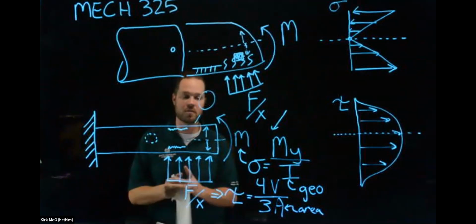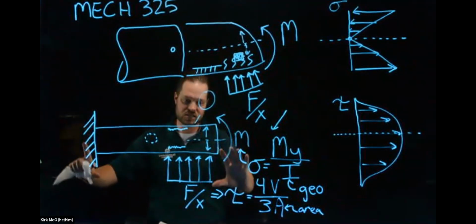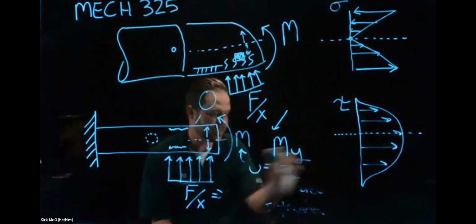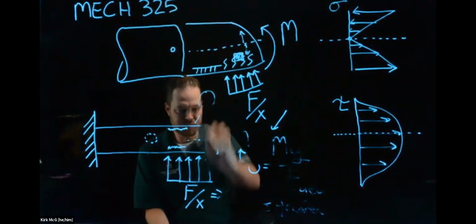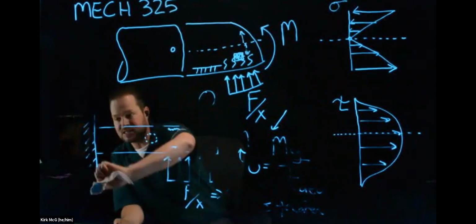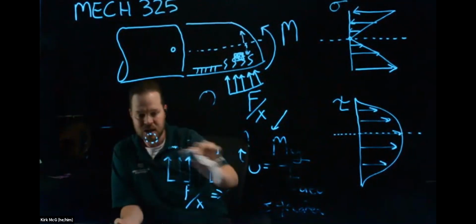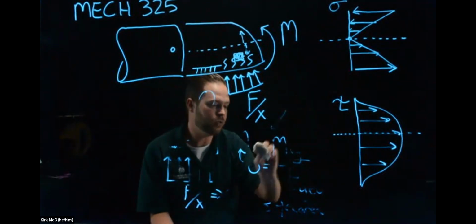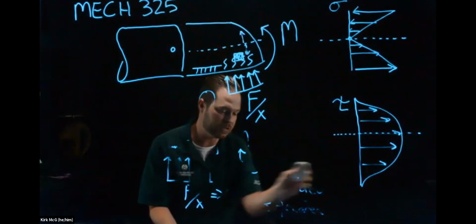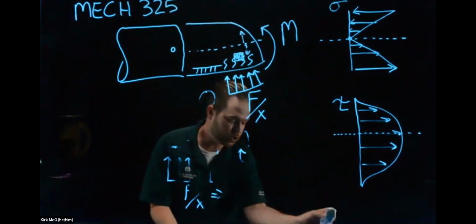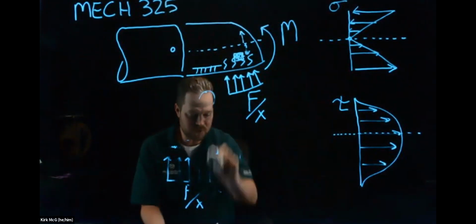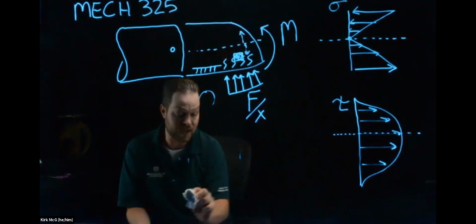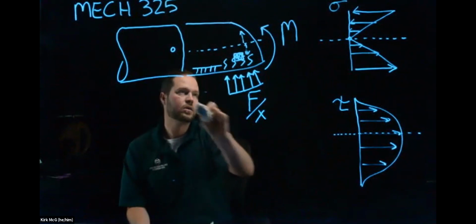So we realize that there is different stress distributions as a function of applied load, as a function of geometry, okay? So how do we use that as a mechanical engineer to do design? Well, we continue with our complexity. So remember this, please, okay? So what we're going to see is that as we probe specific regions of interest inside our simplified beam, we want to look at discrete ROIs. And the reason why we want to do that is because we want to build a map of the stresses inside our component, because those stresses, what we'll see in a moment, are what dictate if a part is going to fail or not, okay?